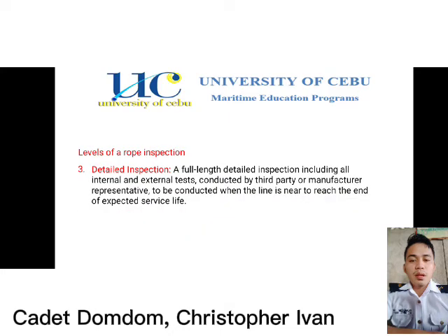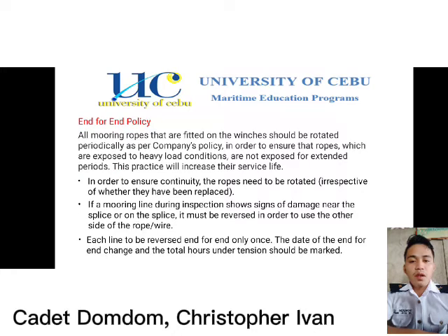And next is the detailed inspection. A full-length detailed inspection includes all internal and external tests conducted by a third party or manufacturer's representative, to be conducted when the line is near to reaching the end of its expected service life.